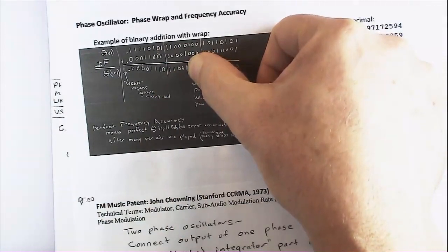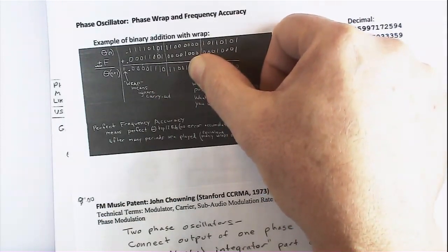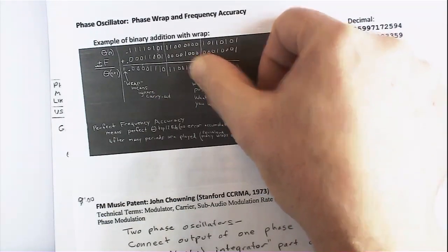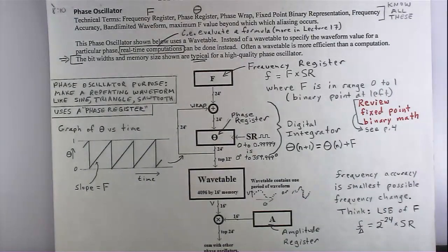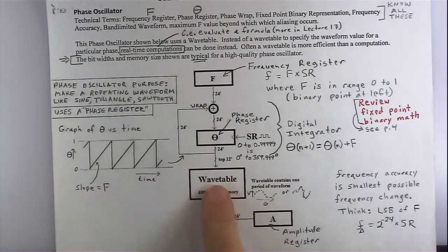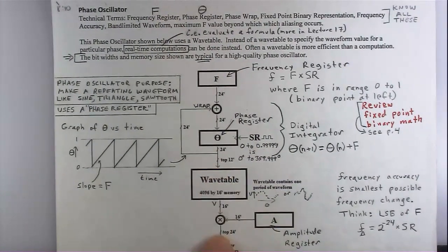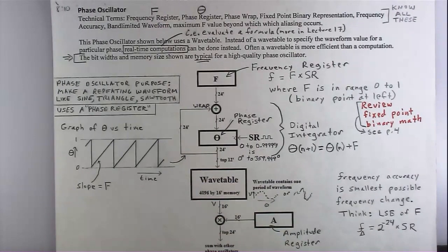You're jumping over a lot. You're not just reading every neighboring sample. You'd have to be playing at a fraction of a hertz to do that. So it'd be way, way, way sub-audio if you're hitting every sample. But you're going through there, so you're playing like every nth sample, where n is not an integer, I guess. You're skipping over some samples, you read something out, and then it goes to the D to A converter. It gets a low pass filter in that process, of course. After converting to analog, you've got to get rid of all the high frequency copies of your spectrum, but all that stuff happens and you're good.